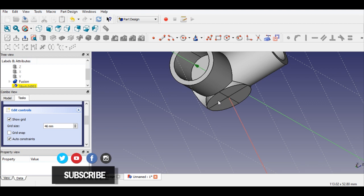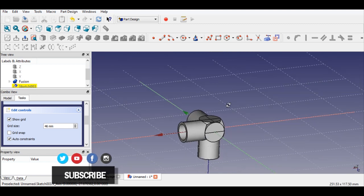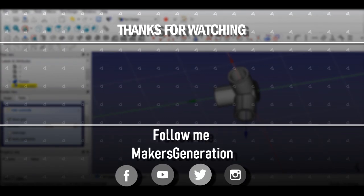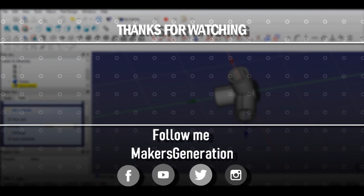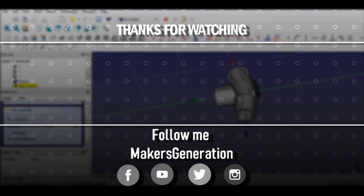You click on that, guys, and if you look at the schematic, it was 16 or 17 millimeter for the depth. So I click here on 16, and you can even try 17. I think it was 17. So have a look inside. It's pretty clean. Yeah, it's pretty clean. I click on OK. So I've done it for Z. Now let me click on this one now.